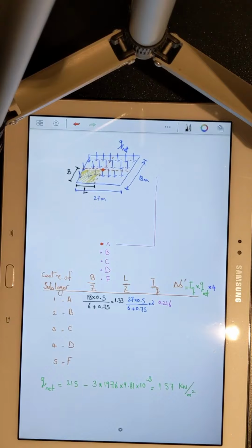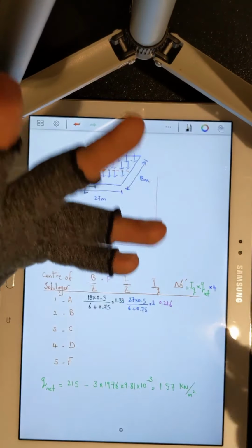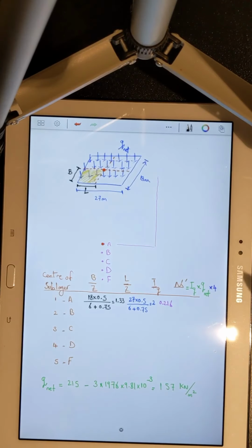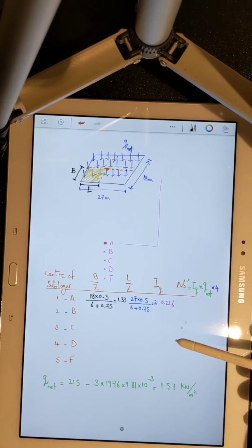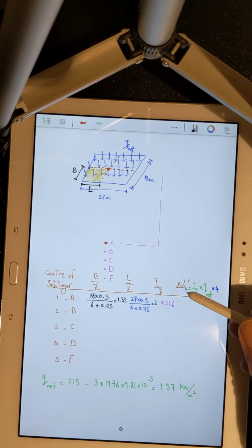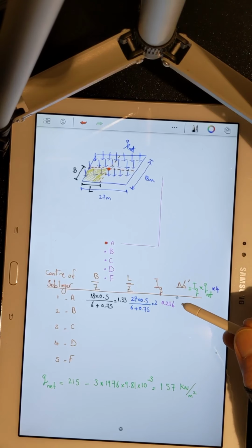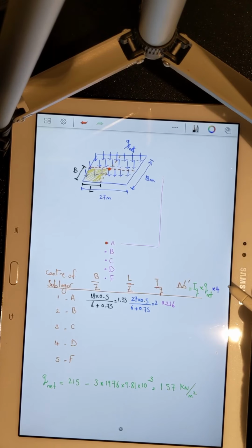You can either use linear interpolation if you are moving between numbers, or you can be conservative and go for the maximum I sub q for the numbers that you have. Between 4 numbers, you can go for the maximum value, but that is really the conservative design.